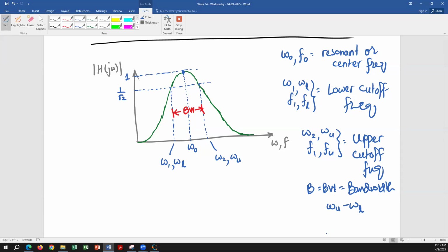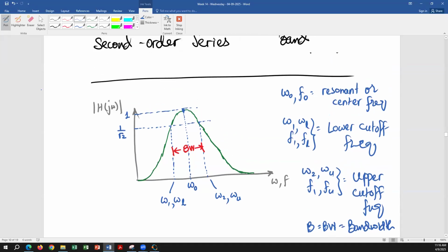Now, in general, we also have the stop frequencies for every filter. We are just discussing the cutoff frequency in the pass band. Also, by the way, the band of frequencies where all the frequencies are passed is called the pass band. Then you have a transition band, and then you have a stop band. There are 3 bands in every filter.